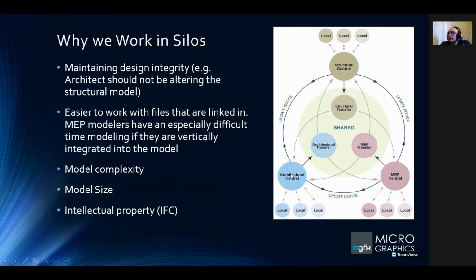Now, while that is irritating, what would be catastrophic is if an architect had to delete a structural column or a beam and the building falls down as a result of that. So the structural engineer has to take ownership of his model, the MEP engineer has to take ownership of their model, and any other discipline that's involved, especially where it's critical to the building's integrity, must have total control and ownership of their model. And that is good practice. That is one of the reasons why these BIM protocols are set up, and we understand that from the beginning of the project.